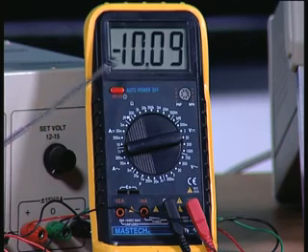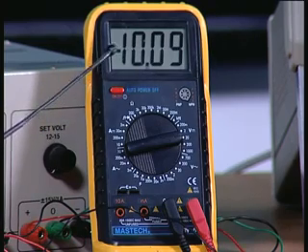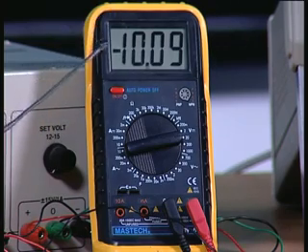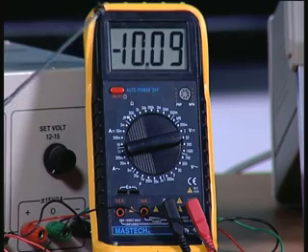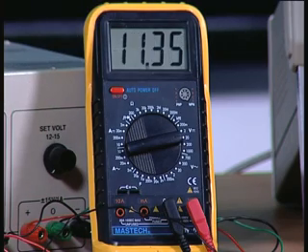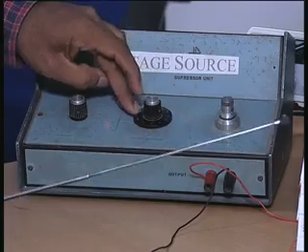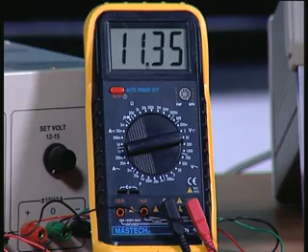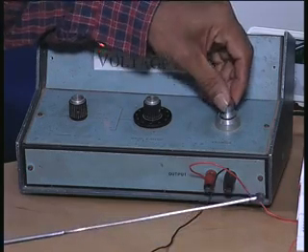That means it has gone to the minus VCC, because 2 volts is larger than 1.2 volts, and therefore the inverting input voltage is larger than the non-inverting input, and therefore it goes to minus VCC. To do that, I can also do it another way. Now I bring it back to 1 volt and vary this continuously. There is another dial here which can vary continuously.